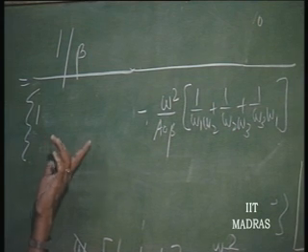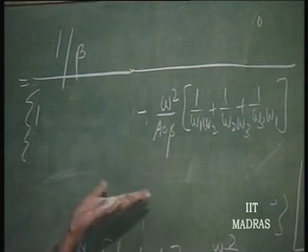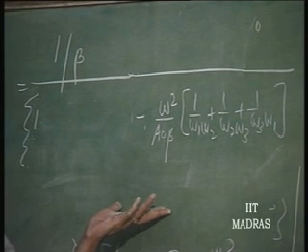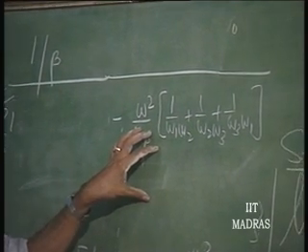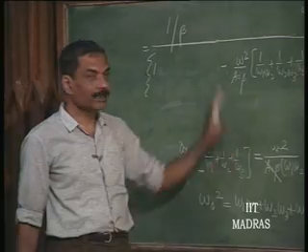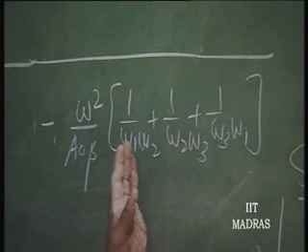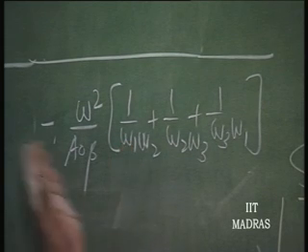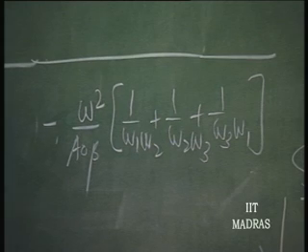Beyond that frequency, this will become negative and it will be the positive feedback region. So, you must have A naught beta sufficiently low such that this 1 minus thing still remains positive. If it becomes equal to 1, there is a danger.